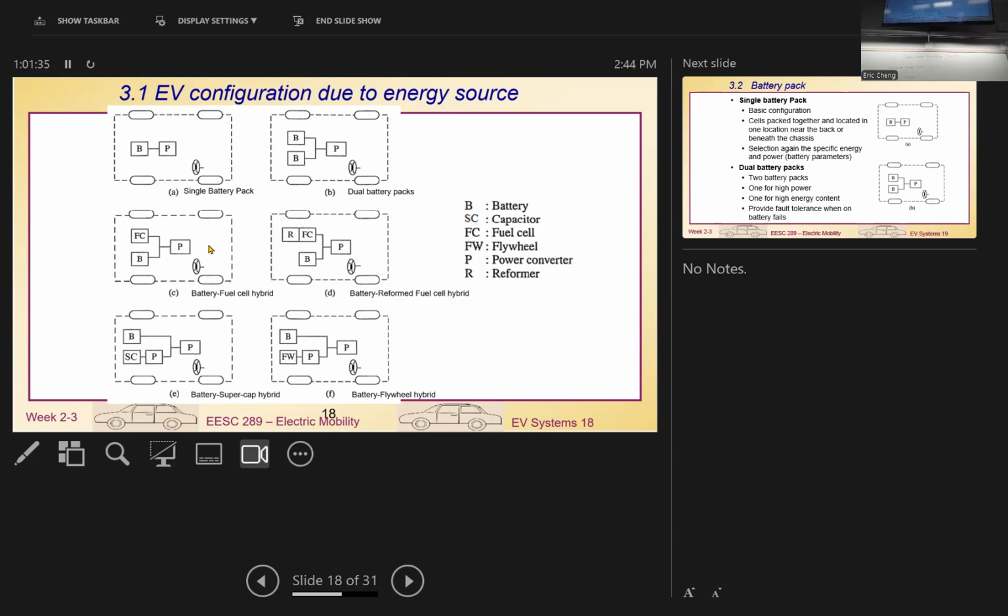The thing is the battery we use is 800 volt. Then for the supercapacitor, if we use 800 volt, it may not be so convenient in the design. Most supercapacitors have quite low voltage. The lithium ion battery voltage is roughly about 3.7, really popular. Although we do have lithium ion battery at 2 volt, most of them will be 3.7 typical. And then supercapacitor, the voltage is much lower, I think 2 point something, usually 2.7.